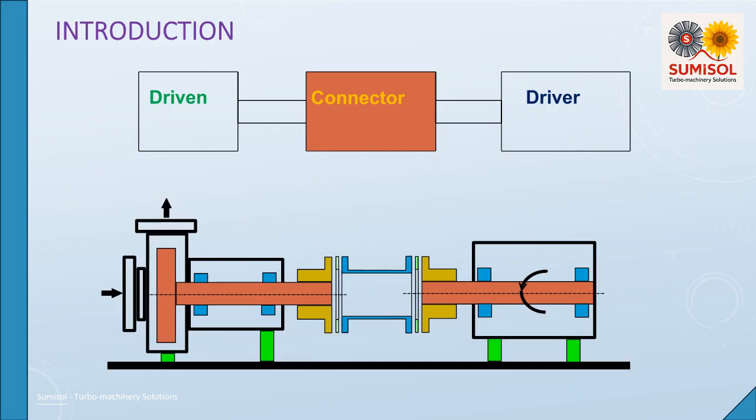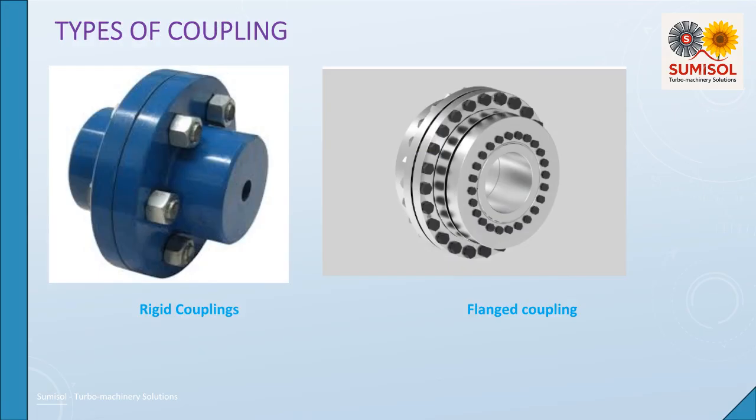A shaft coupling is a mechanical component used to connect two rotating shafts, typically a drive shaft, such as a motor, steam turbine or gas turbine, and a driven shaft, such as a pump, gearbox, compressor or generator, to transmit power. As the name suggests, a rigid coupling permits little to no relative movement between the shafts. Once a rigid coupling is used to connect two equipment shafts, they act as a single shaft. Rigid couplings are used to transmit torque in high-torque applications such as large turbines and gearboxes where slip in the coupling is not desired. A flanged coupling is also considered a rigid coupling.